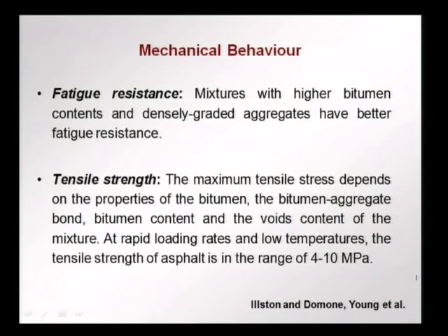We find that mixtures with higher bitumen contents and densely graded aggregates have better fatigue resistance. So, there is some amount of bitumen that is needed. We cannot have all the aggregates so compact that the stiffness is very high and cracks develop. We need some amount of bitumen to facilitate this adaptability to fatigue loading that can prevent cracking from occurring.